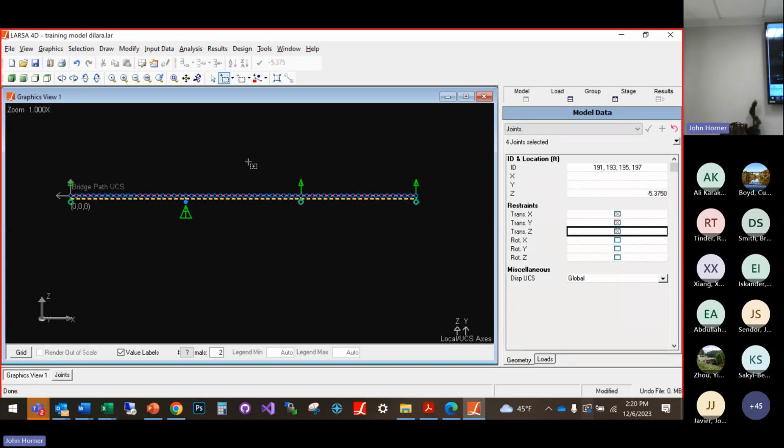You can use this zoom window, and you can change the side plane. Now you can delete the extra members. You need to delete these ones in this panel. To do this, you can use the view to unselect all.